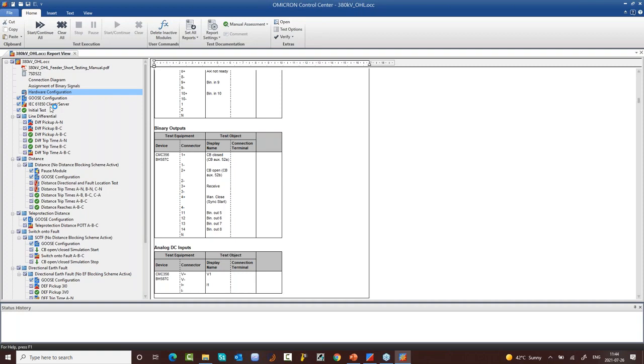From that relay. But luckily here, because I have an IEC 61850 compatible device, it means that I can use this automatically by using a test module called IEC 61850 client server to receive the current and voltage value, and it can make the assessment automatically. After that, I have the line differential to get the backup.